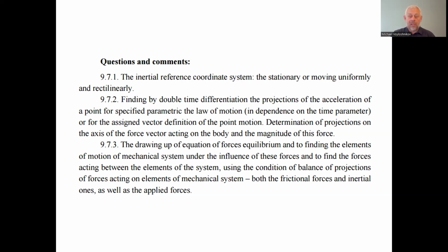So to be more exact and honest, to use the D'Alembert concept and to decide the direct or inverse issue of dynamics, to find the forces having the elements of the motion of the mechanical system, or to find the elements of the motion having the external forces, in the balance equations in accordance with the D'Alembert concept we have to account not only for the forces of inertia and maybe moments of inertia of the moving inertial elements of the system, but also the forces resisting movement, that is, the efforts of friction to the motion.